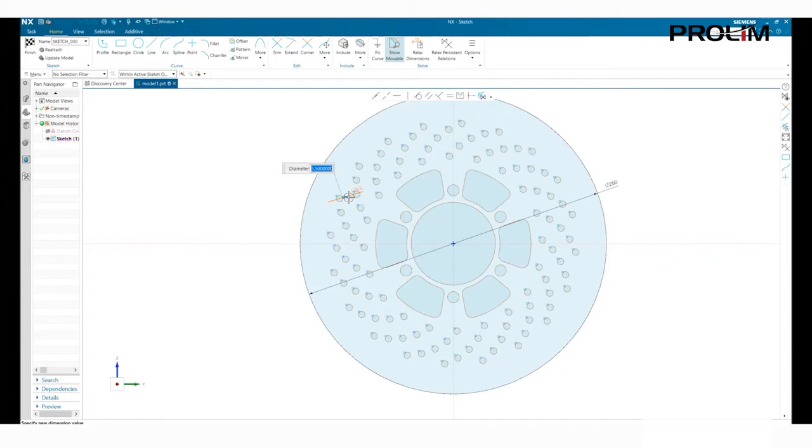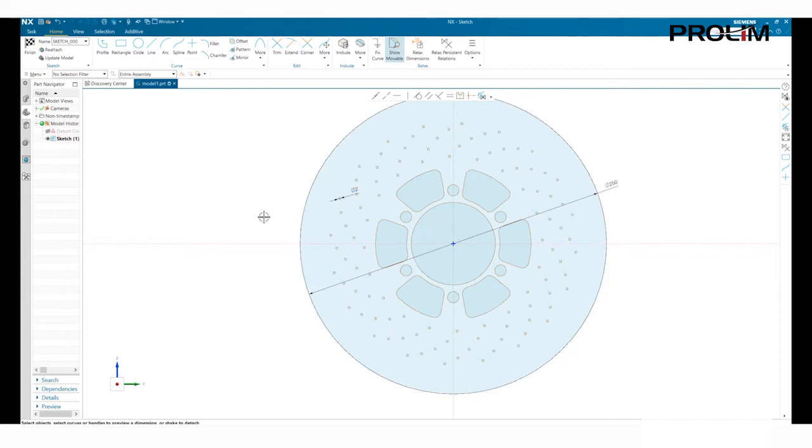And let's just say, I don't know, 2, just to make it a little bit tinier so you can see here. You notice that it retains all those relationships. Later on, we'll get into how we can relax those relationships. But as you can see here, it is a very intelligent feature. It comes in and recognizes that these are, in this case, a pattern for all those holes and offsets and things like that. It's a nice little feature that allows you to quickly come in and take geometry imported from another system and be able to use it for what you need.